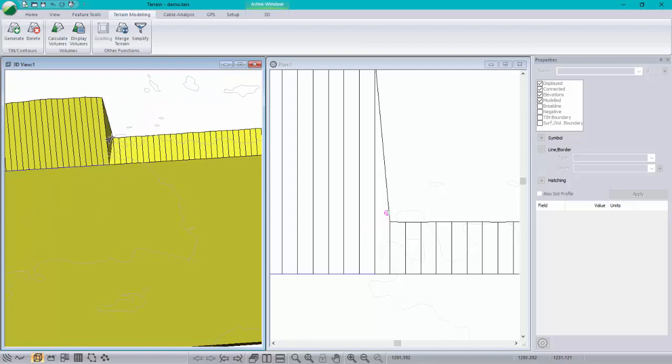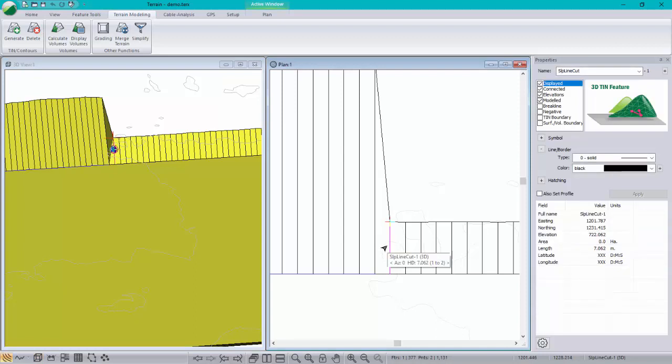I like that surface. One little thing, how would I make this slope here a little less steep? The correct thing to do here would be to take this slope line, extend it out to the ground here, and then take this slope line and do the same thing. And then we'd have slope lines that extend out at different angles. Okay, so that's a little tricky. We could type in coordinates and pick up the elevation. You can see it by hovering here, but I'm going to do something a little bit simpler.